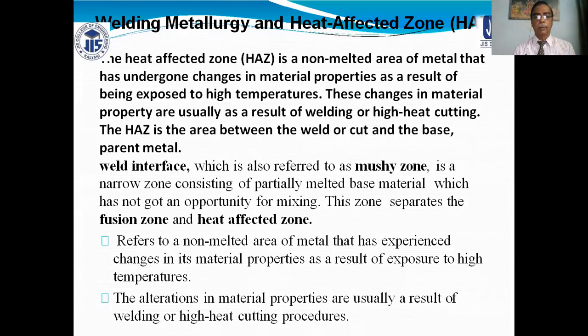The weld interface, which is also referred to as the mushy zone, is a narrow zone consisting of a partially melted base material, which has not had an opportunity for mixing. This zone separates the fusion zone and the heat affected zone. The HAZ refers to a non-melted area of metal that has experienced changes in its material properties as a result of exposure to high temperatures. The alterations in material properties are usually a result of welding or high heat cutting processes.